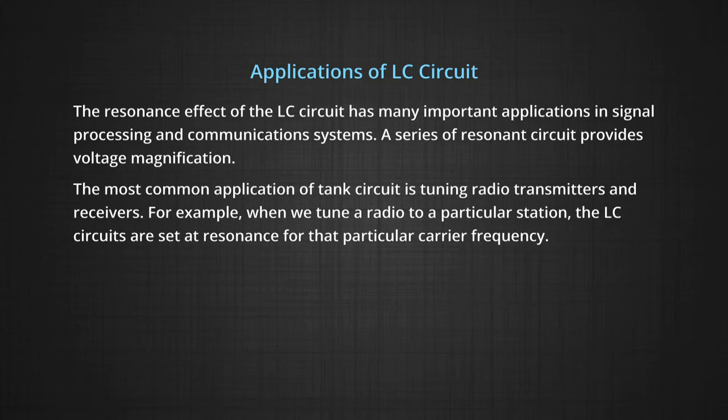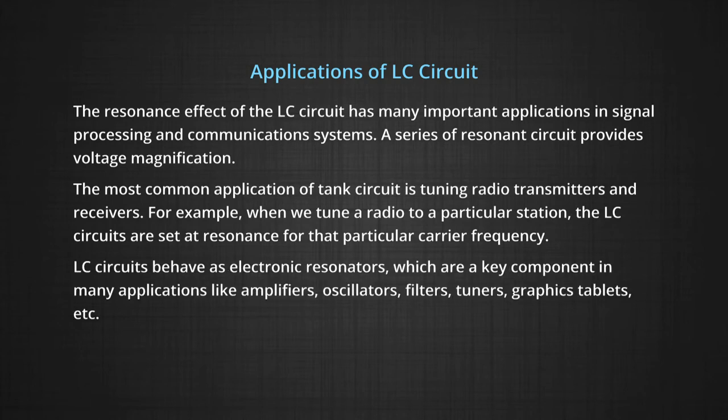For example, if we have to tune a radio to a particular station, the LC circuit is set at resonance for the particular carrier frequency. LC circuits also behave as electronic resonators, which are a key component in many applications like amplifiers, oscillators, filters, tuners and graphic tablets and many more.